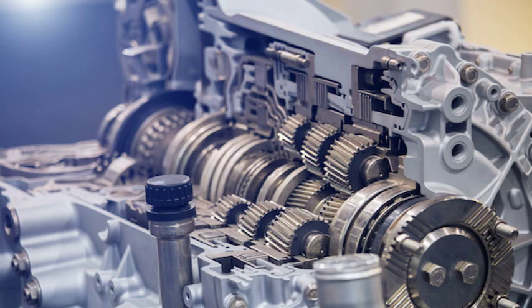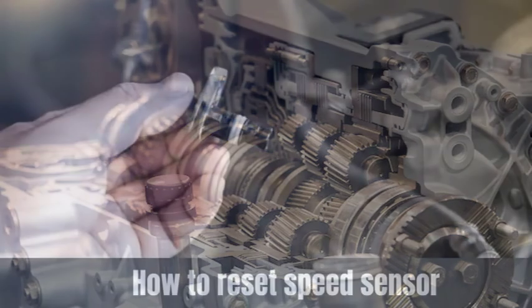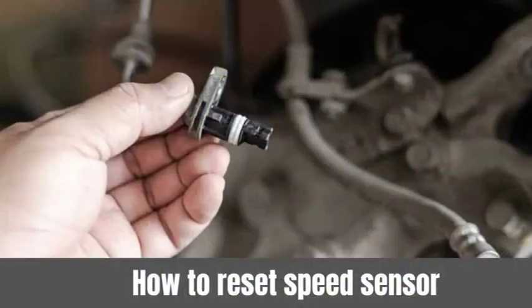What are the common symptoms of the P0720 code? The most common symptoms of the P0720 code are an illuminated check engine light, a flashing check engine light on some Ford vehicles, a speedometer that does not work properly, a transmission that does not shift properly, a loss of power.